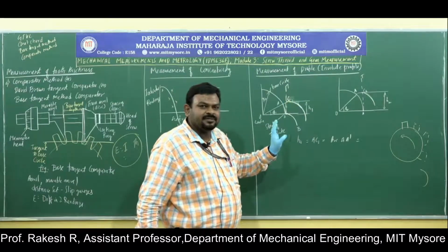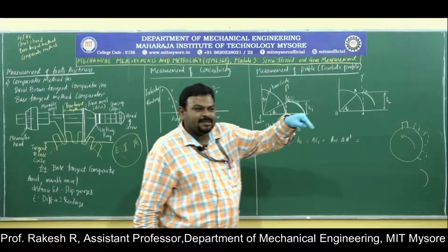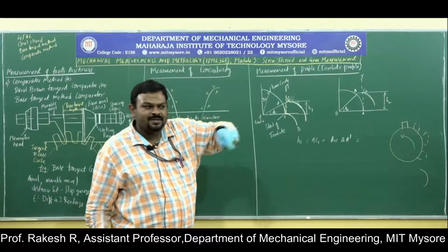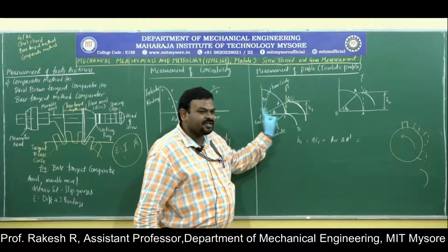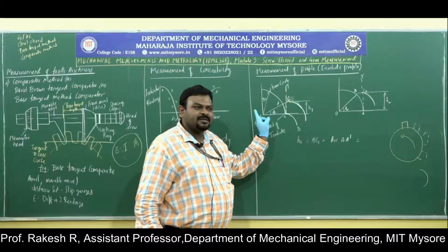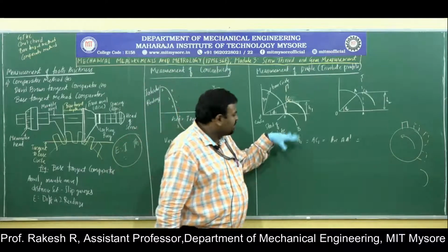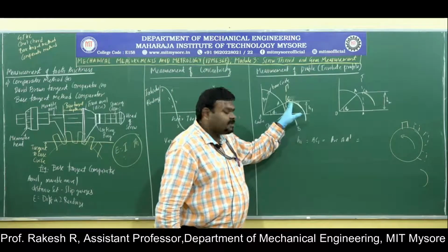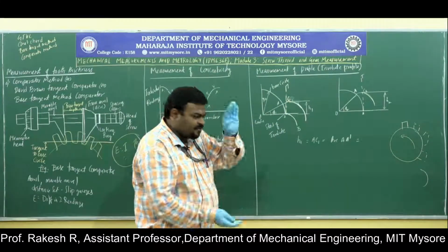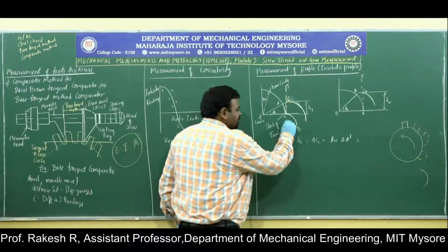Next it is indexed. It is just like having lunch in a group. The first person will be serving, then after that you will be moving. So instead of moving linearly, here it is a rotation. First tooth manufacturing over, then again it is indexed. How much angle it is to be indexed, and again the milling calculation will be there. Then the second person will be coming and the second tooth will be manufactured. Then the third person, third tooth, fourth person, fourth tooth. Like that it is being rotated, indexed.